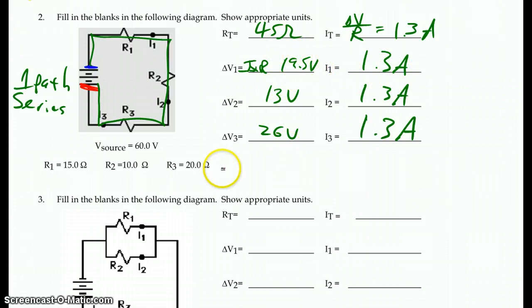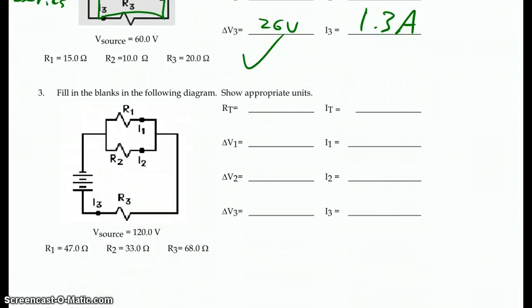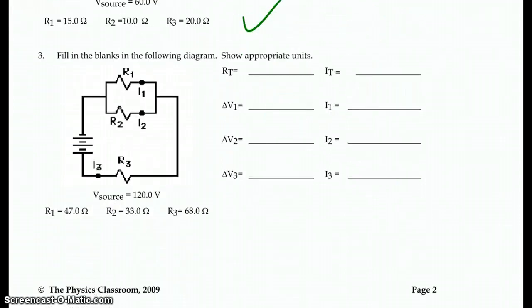We are definitely on the right path. So that's it for that circuit. That's all it takes for a series circuit. Now, a series circuit's pretty simple, so that's why whenever we have the following type of circuit, we usually get rid of the parallel first and then solve it as a big series circuit.